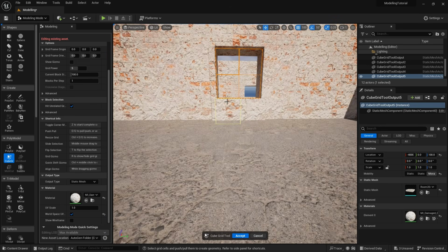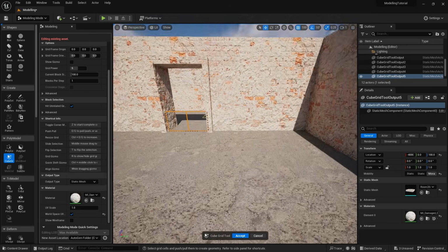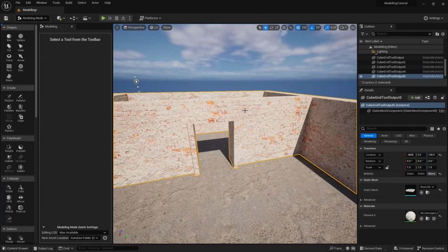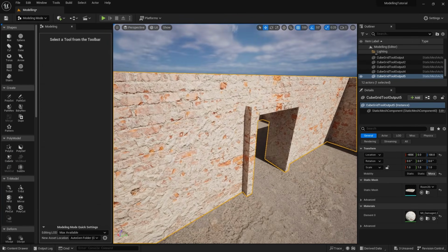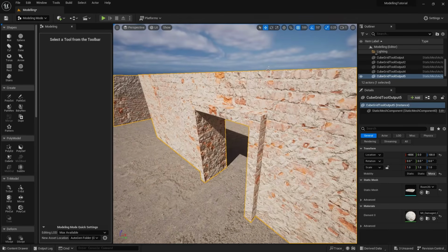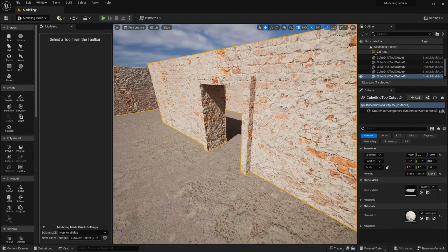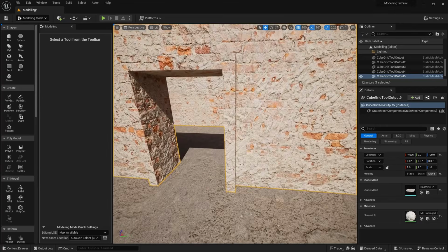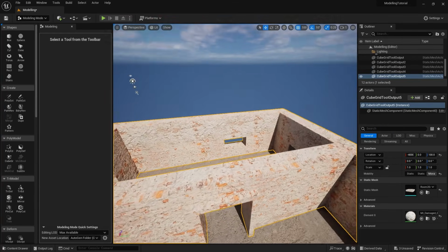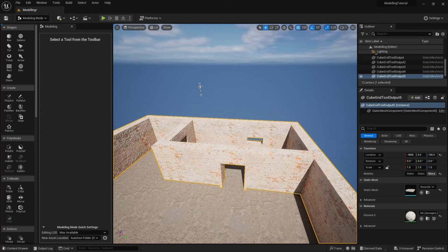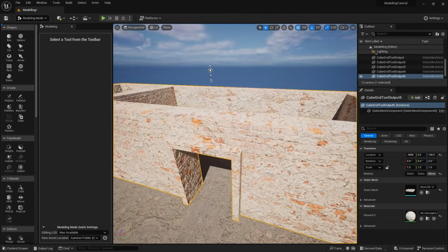Okay, so I forgot to do the bottom bit here, so Control to pull out, Control to push in, and there what I've done is recreate the opening. And now you can see if I get up slightly closer, I've created a finer detailed structure here. So the cube grid's pretty useful for creating not just large scale detail but fine scale detail.